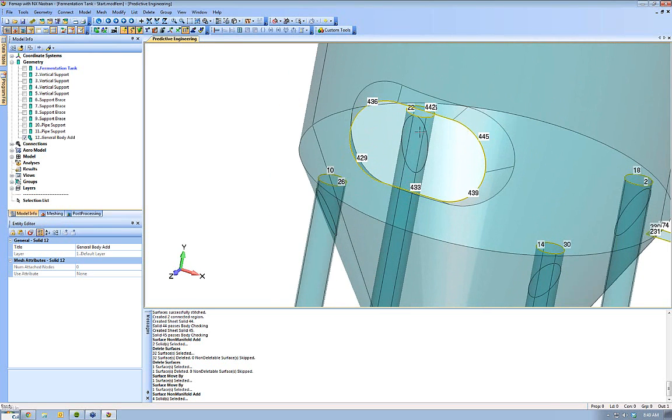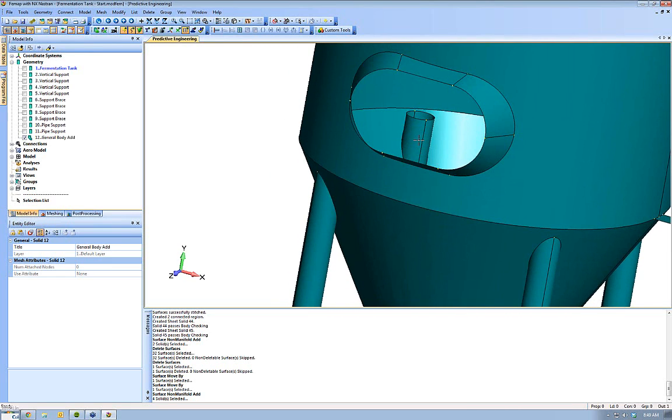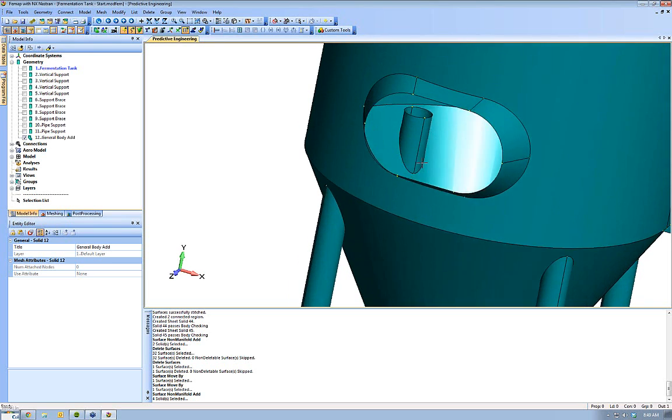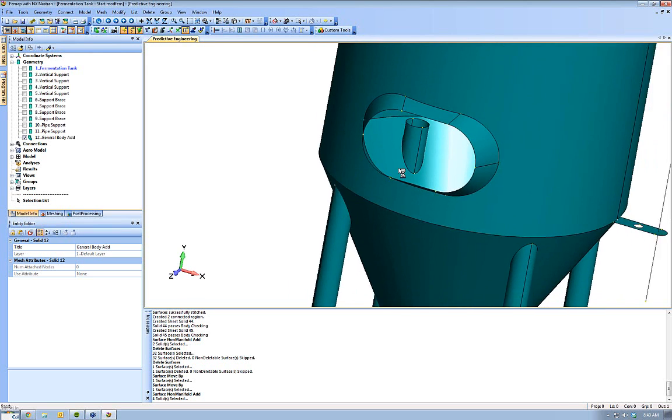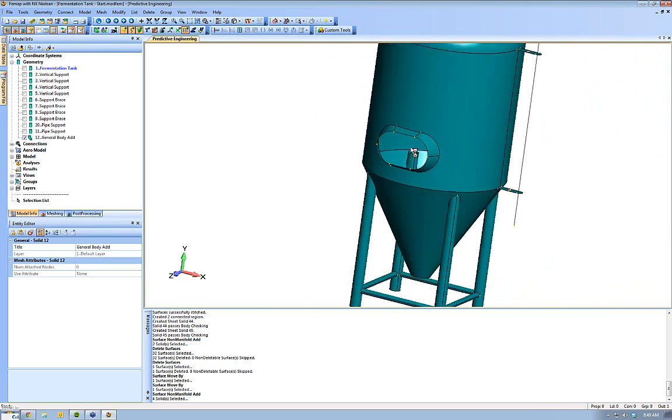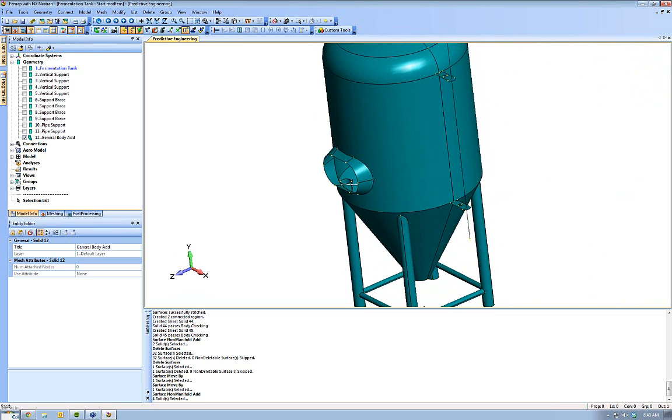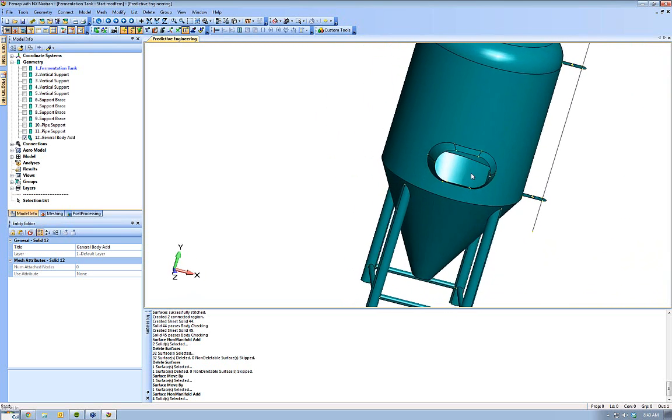Again, I always like to have it overlap, like these pipes penetrating through, to ensure that the parts are going to connect and delete off the extra material, rather than leave a gap and later on in my project discovering that I have a gap and something's not connected. So this is a technique that requires you to delete surfaces afterwards, but you're guaranteed to have this connection. And to get inside of this tank here and delete some of these surfaces, it's going to be tricky peeking through this little window.